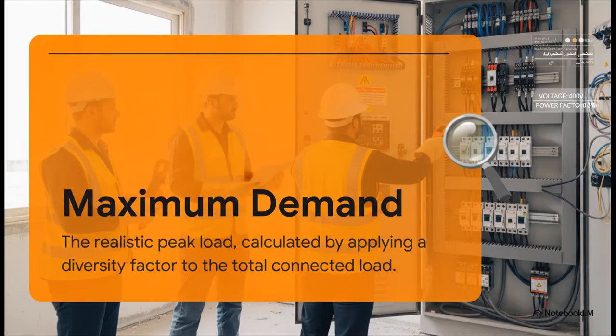You know, one of the biggest mistakes that leads to oversized and super expensive systems is sizing for the total connected load. The codes don't actually ask for that. What they demand is that you calculate the maximum demand. You do that by applying a diversity factor. Because, let's be realistic, not everything is going to be on at full blast at the exact same time.